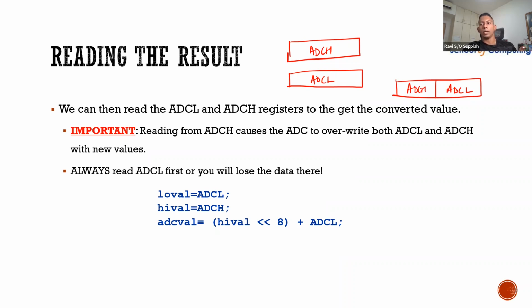In terms of the register, the default setting is such that for ADCL you have 8 bits, and those 8 bits come here. For ADCH, you have 2 bits, the lower 2 bits over here. What I need to do is make sure these 2 bits come here, 2 bits here plus the 8 bits here.